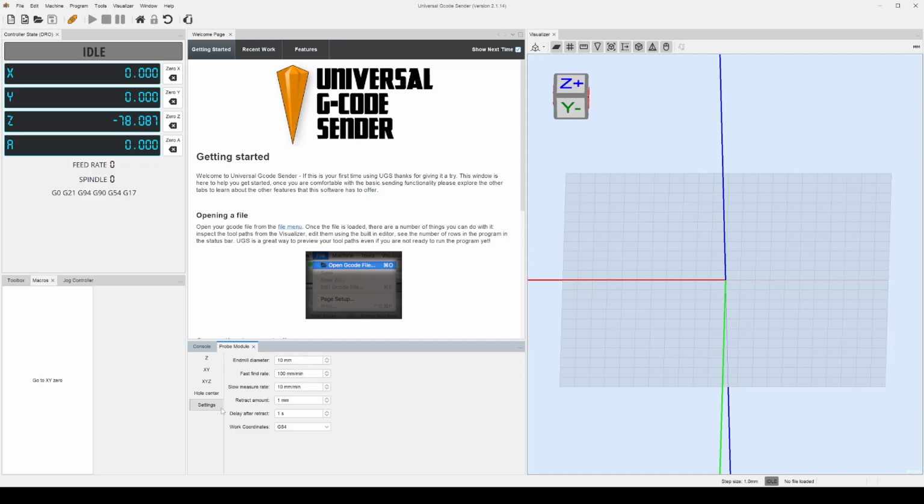I wish that OpenBuilds had this. I mean, this one's easier also to set up. It gives you a little more information on what the retract distance and the delay are. So if you're doing the XY, probe in this distance and probe offset, so when you go to these settings, it shows you what's actually going on.